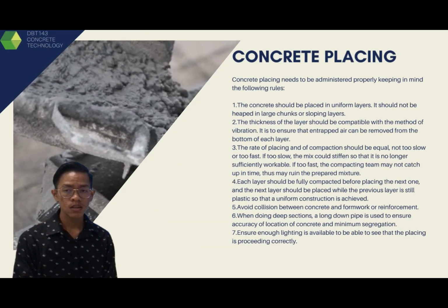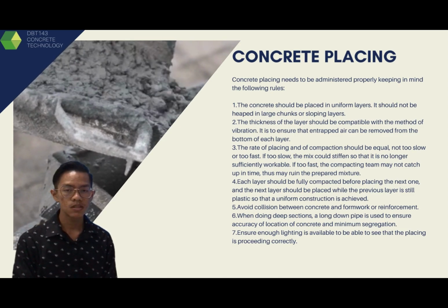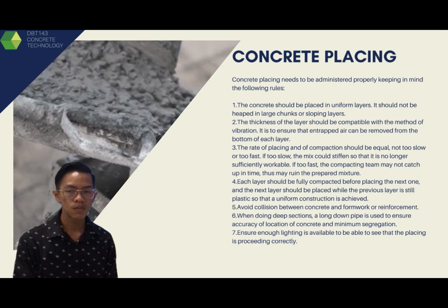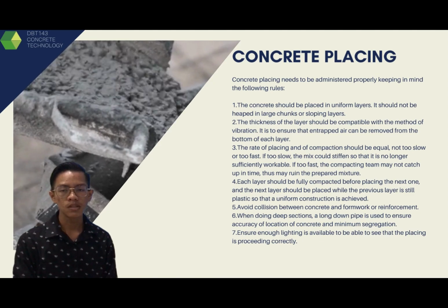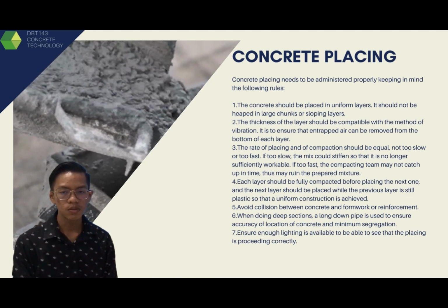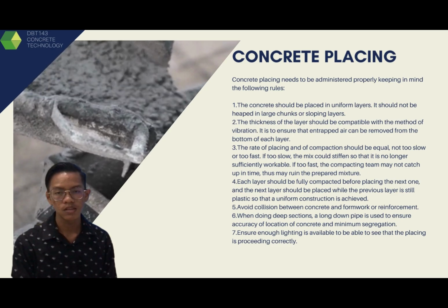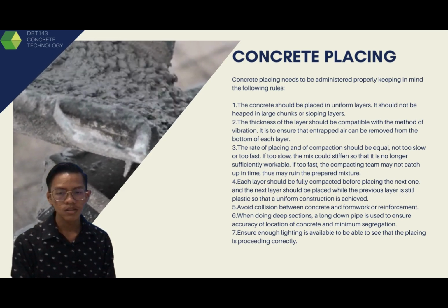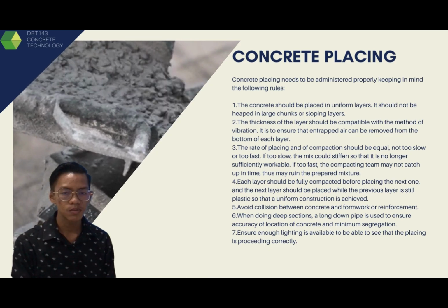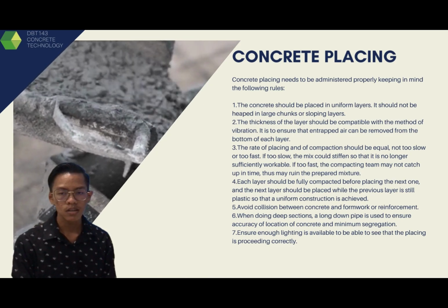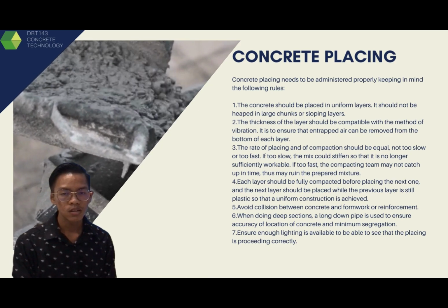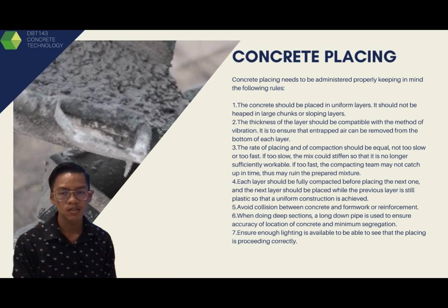Concrete placing. Concrete placing needs to be administered properly, keeping in mind the following rules. Number 1. The concrete should be placed in uniform layers. It should not be heaped in large chunks or sloping layers. Number 2. The thickness of the layer should be compatible with the method of vibration. It is to ensure that entrapped air can be removed from the bottom of each layer.